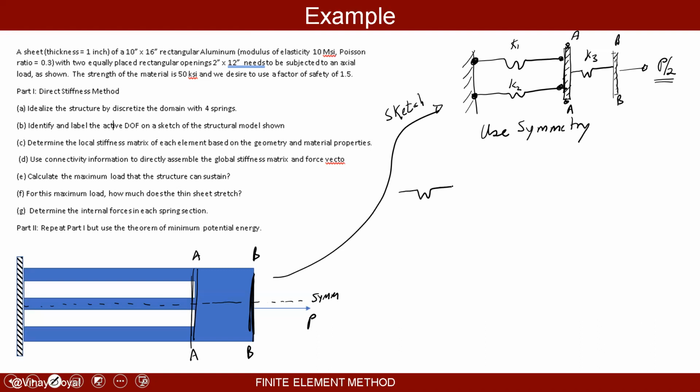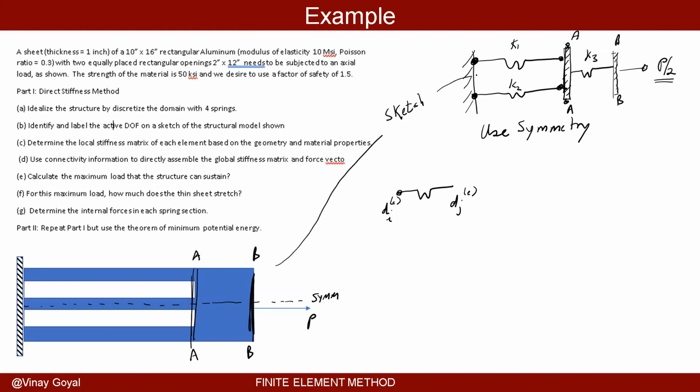That's for each spring. On node i, on top of the displacement, we also have a reaction force, Ri, represented by the arrow pointing to the right. And also we have an internal force, which is represented by Fi, right?